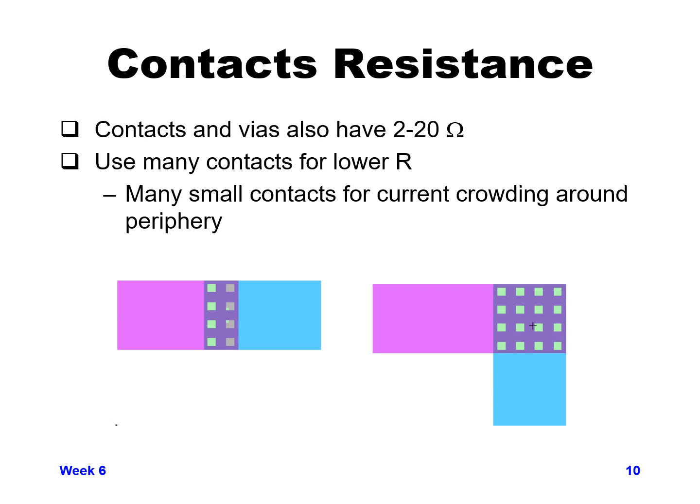So using more contacts or more vias in parallel with each other will lower your resistance, and in some cases your contact or via resistance might be as much or more than your wire resistance if you have a wire that's not very long, for example. So always keep track of contacts and vias; they can be a significant issue on certain types of nets in certain situations.